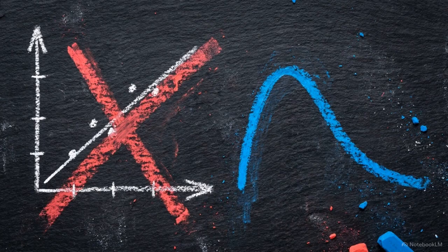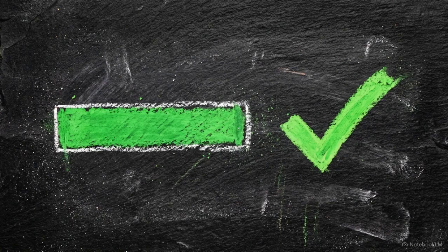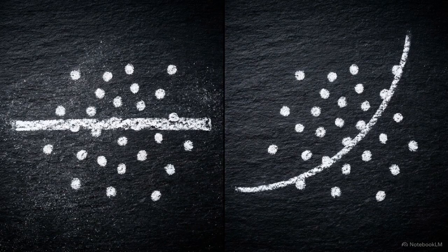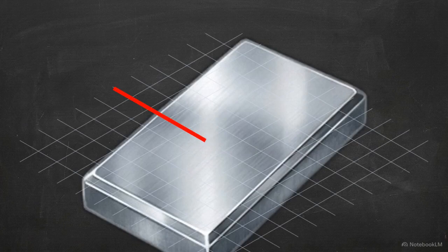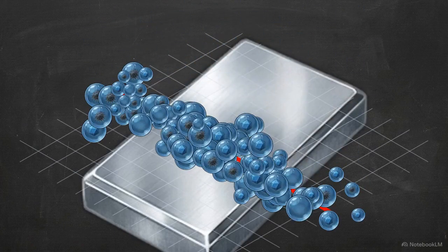With the accurate curve established, the D10 value is discarded and replaced by the delta value. The delta value represents the true dose needed for a 1 log reduction under the Weibull curve. For aerosolized hepatitis A, the required 279 nanometer delta sits between 5.21 and 6.67 millijoules per square centimeter. The Weibull model captures the biological reality that the linear D10 model ignores. Industry-standard D10 values fail to account for the physics of wet, aerosolized viral deposits on industrial surfaces.